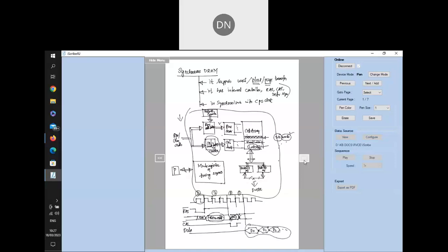In a block transfer, for the first word of data transfer, you require multiple clock cycles. You may require 5 to 6 clock cycles. First apply the RAS, keep the row address on the address bus, then generate CAS, keep the column address on the address bus, then give one clock cycle for the data to come. After that, all the further words will keep coming every clock cycle.